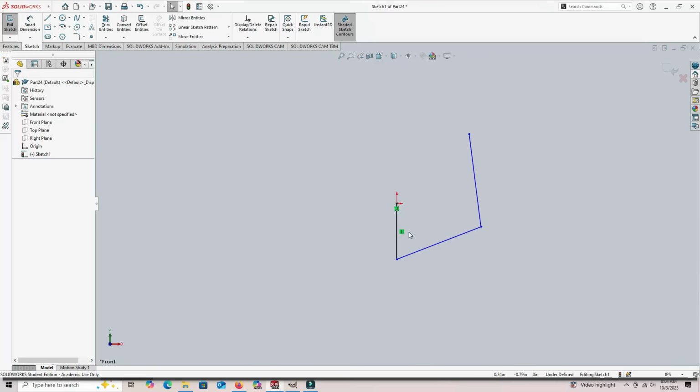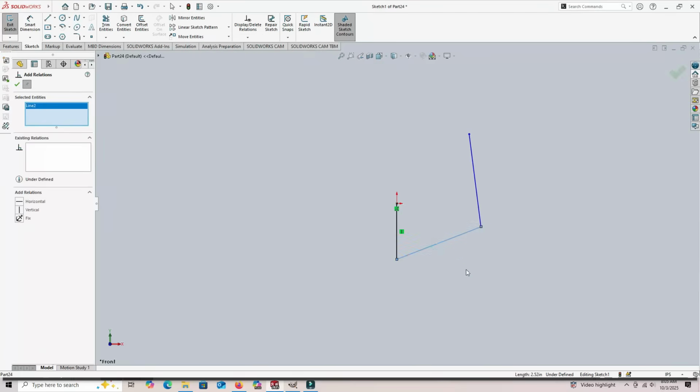No problem. I can click the green check mark, and now I show that that is a black line with that vertical relationship again. Let's go back, and let's say that I wanted this line to be horizontal. I could choose that, and it will snap it around, potentially fixing a mistake that I made by misclicking out in the field. You can also choose multiple features such as this line, and it will give you a few more relationship options here.